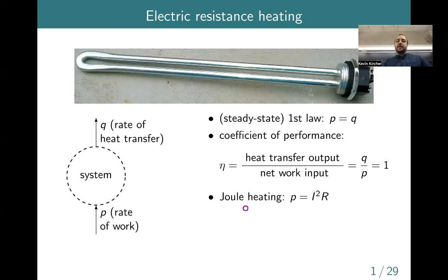And the physical mechanism here is what's called Joule heating. So probably should have put an illustration of this in here, but within this solid, atoms basically are arranged in a lattice, and they have intermolecular bonds, quite strong, holding them in a fairly rigid position. And then electrons flow through there, and as they're flowing through, they bash into atoms that are making up that lattice structure. And that causes things to vibrate, and vibrations at the micro scale manifest at the macro scale as temperature increases, basically. So that causes the thing to heat up.